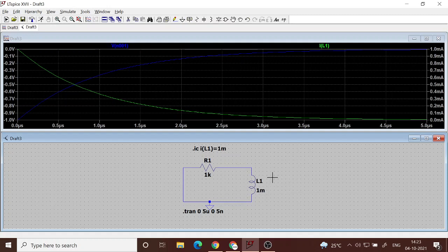Okay, so there is a relationship between inductor voltage and inductor current, so that it calculates and then it finds out. Okay, because the current cannot remain the same, it has to go to 0, so there is going to be a rate of change of current, which is basically the slope. So this slope, as you can see, it is negative, it is going to decrease, the current is going to decrease, and therefore the voltage has to be negative. Okay, and as the slope reduces, the voltage reduces to 0. So voltage is basically the slope of the current waveform in inductor.